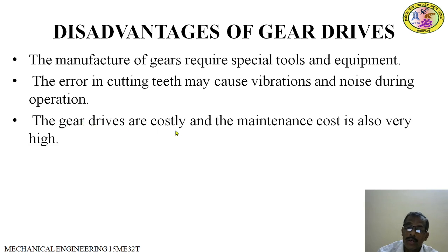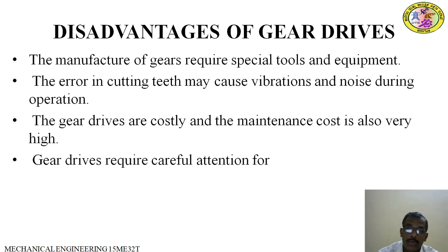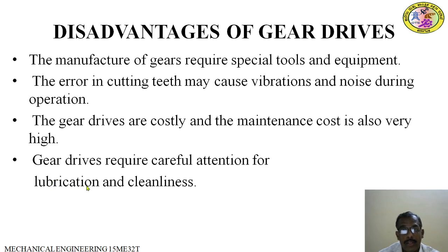The gear drives are costly and maintenance cost is also very high. So what type of maintenance? Gear drives require careful attention for lubrication and cleanliness. We have to lubricate the gear drives frequently and change the oils in gear drives. Then only they will have good performance. And cleanliness, we have to maintain that one.